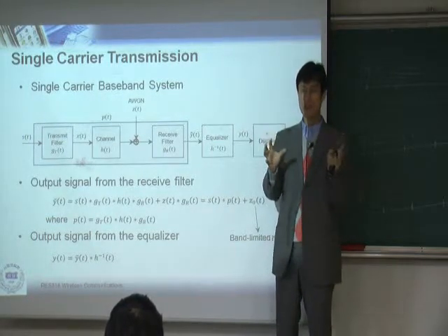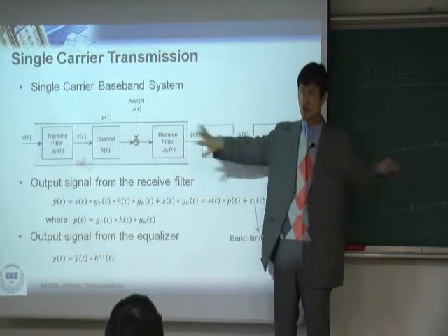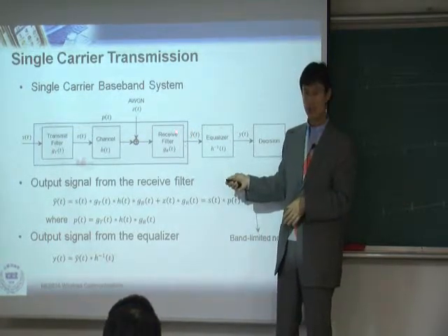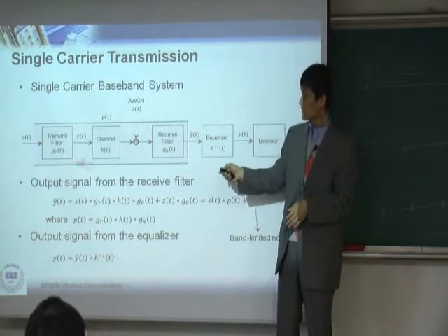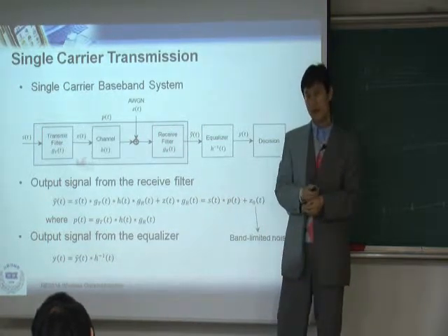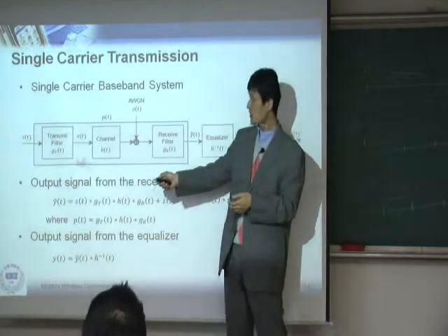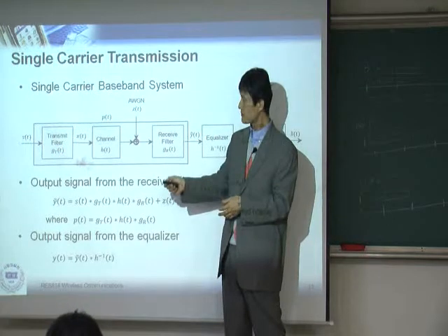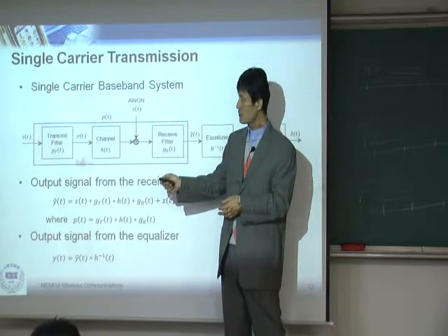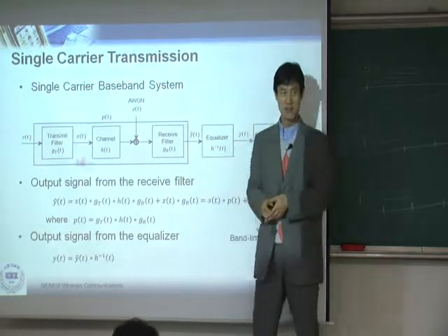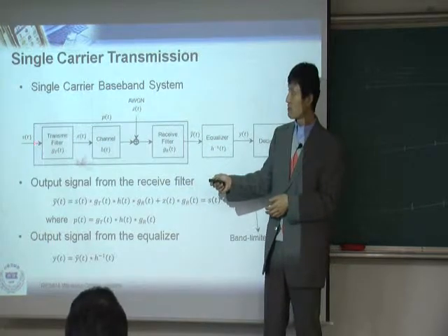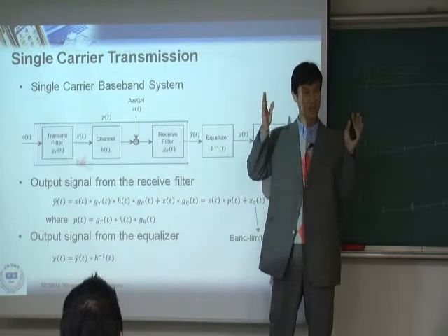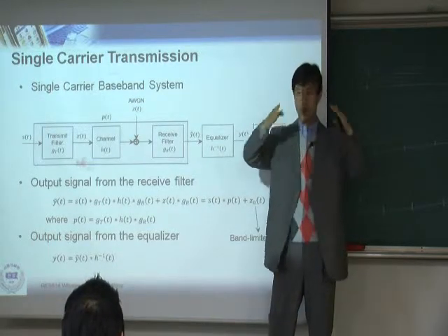So you have to manage the spectrum so that you remove all the others. I want to look at only my band. That's why you need it. Some of the spectrum management here, and the transmit filter. One of the reasons is that if this is binary data or some symbols after modulation, and you just transmit this as it is, then you cannot make the right spectrum. Your spectrum may have a peak somewhere. Your spectrum may have a long tail.